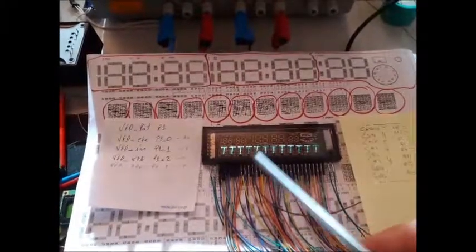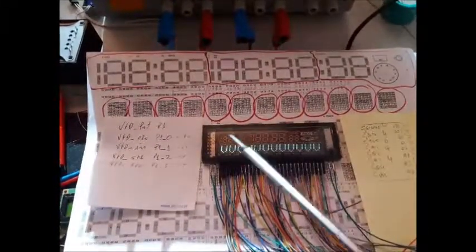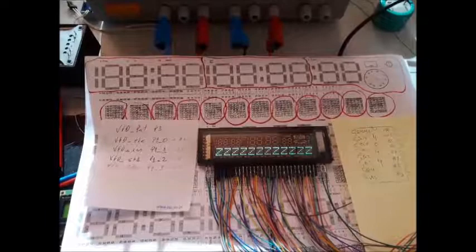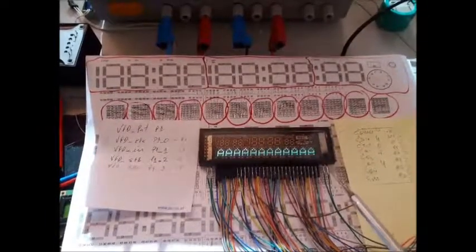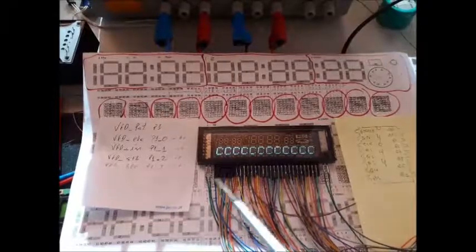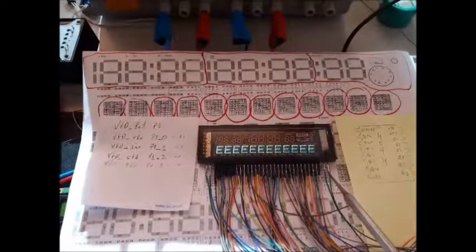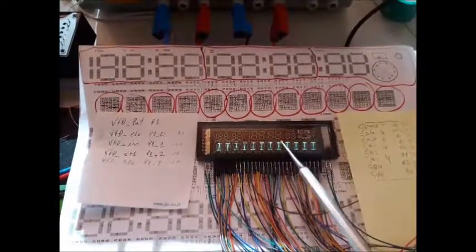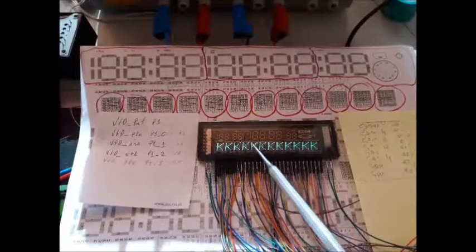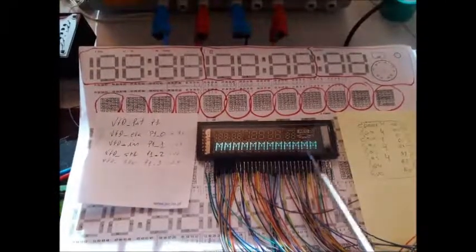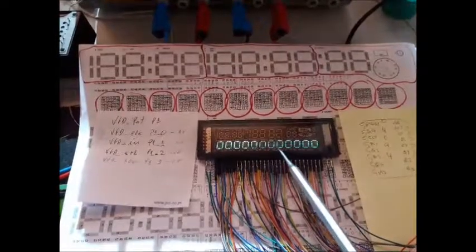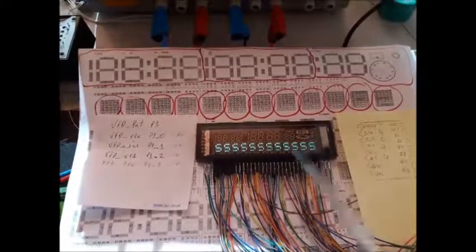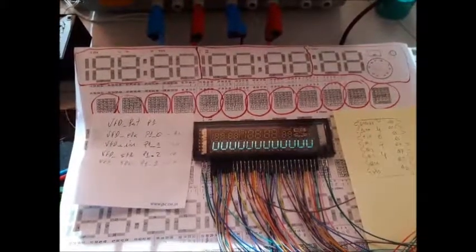And they can have more filaments, 3, 4, depending on the size of the display. To power the filaments at this moment, I'm using 3.5 volts DC. If it's possible to power the filament with AC, it is better, because you don't notice the small shadows in the anode when it's bright, okay.